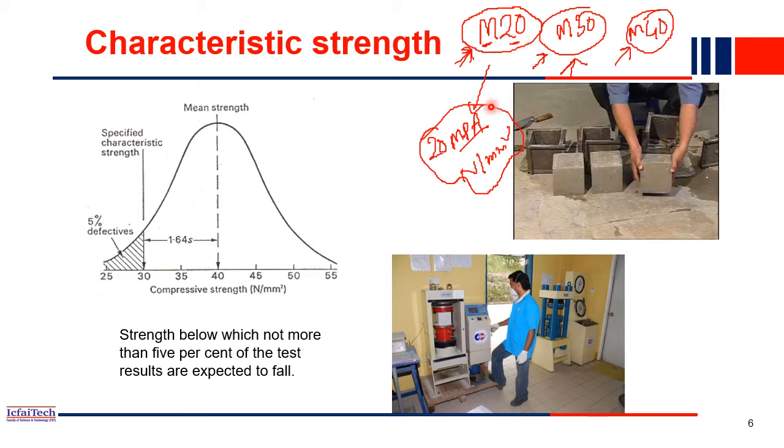Okay. Now, as I mentioned, concrete is actually made up of 3 or 4 different types of materials. One is coarse aggregate, fine aggregate, sand, cement. Now these materials will be mixed at a site, and so many uncertainties will be there in the strength, because the aggregates are also collected from nature. We break the hills and we collect the stones. Similarly, sand also will be collected from a riverbed or somewhere. So these materials will have a lot of impurities with them. Coarse aggregate also will have impurities, sand also will have impurities, right?